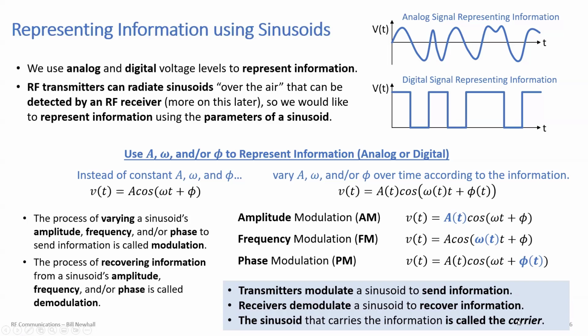So if you have a modulated carrier, you're changing the amplitude, frequency, and/or phase of that carrier, that sinusoid. There are some specific uses of the word carrier that I won't get into. The carrier can actually look like it has disappeared from the modulated signal for certain modulations, but we'll leave those details for later.